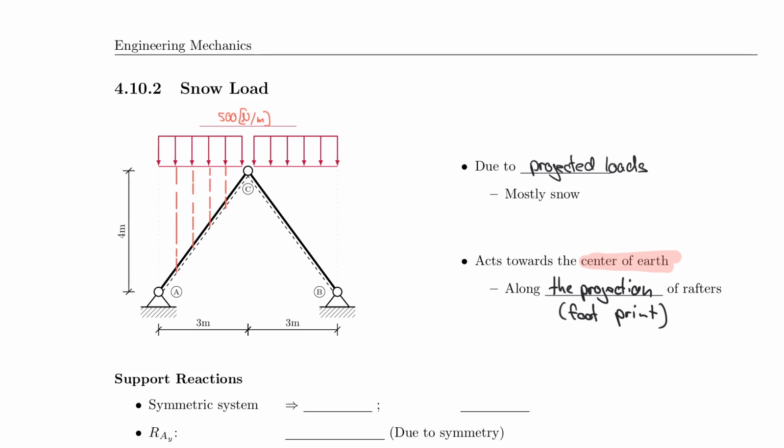You may imagine that Florida has very different snow loads than Colorado, and in fact, in Colorado, different regions or different elevations have different snow loads. And when they create these snow loads, nobody wants to tell you anything about how your roof is pitched, right? Because the architect decides that, or maybe the engineer. But the snow is always defined based on geographic locations, so it's always based on the projected footprint that the snow produces.